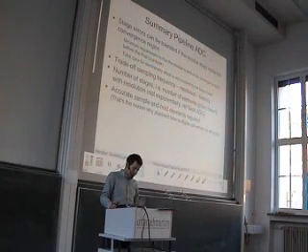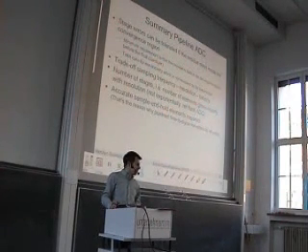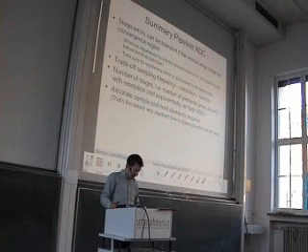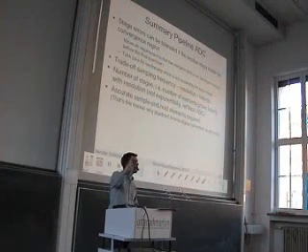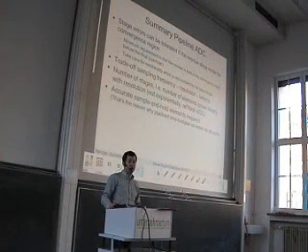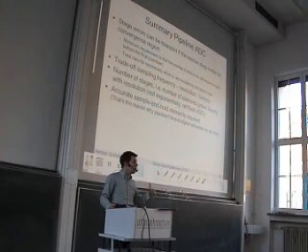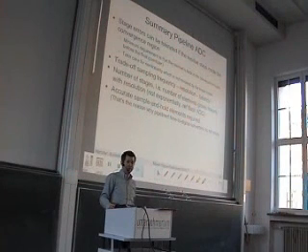Well, and we have seen that all of this pipelining stuff lives from the fact that we can implement precise sample and hold elements, because these are the elements we need additionally in each stage if we unroll this binary search algorithm.